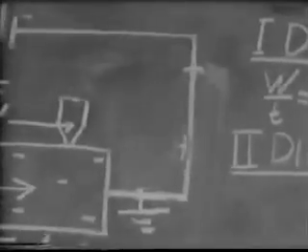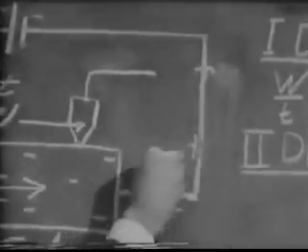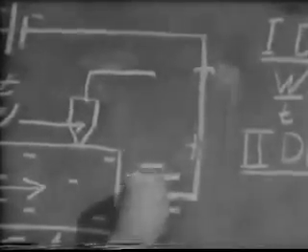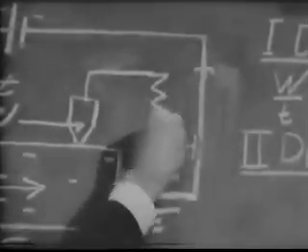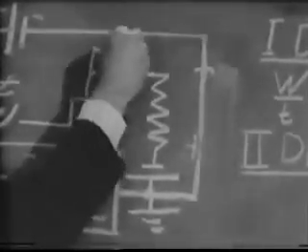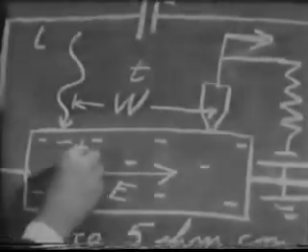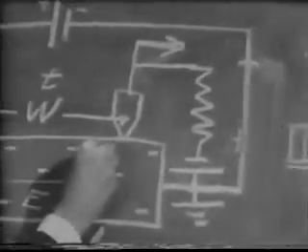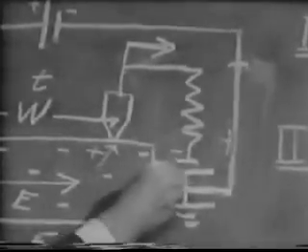To use the point as a detector, we provide a reverse bias and use a resistor to show current changes, and we provide a connection to the vertical scope input here. If a pulse of minority holes passes under the point, the holes are attracted by the negative applied voltage.